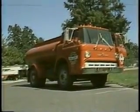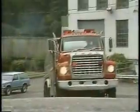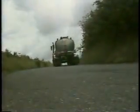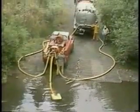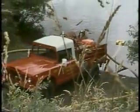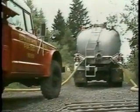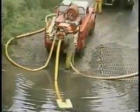Tankers can be manufactured in a wide variety of shapes, sizes, and water carrying capacities. Tankers may be fitted with pumps to draw water from a source directly, or be filled by a pumper or some other pumping apparatus. When utilizing a natural water source, consideration must be given to anticipated water supply duration, firmness of the ground at the takeout point, and the clogging of intakes with floating debris.